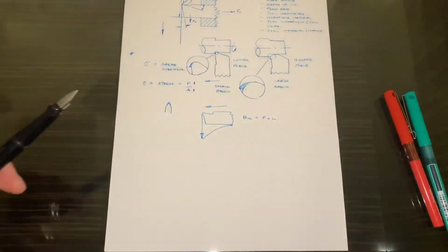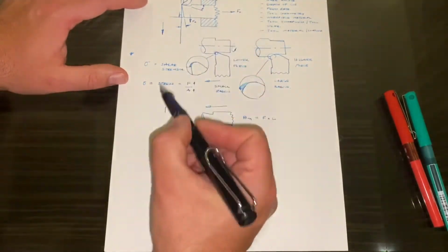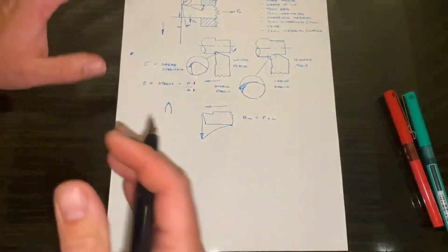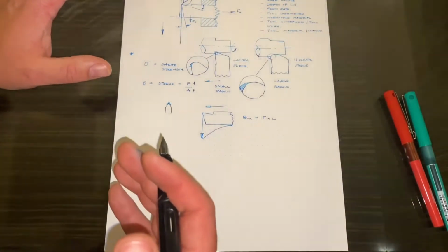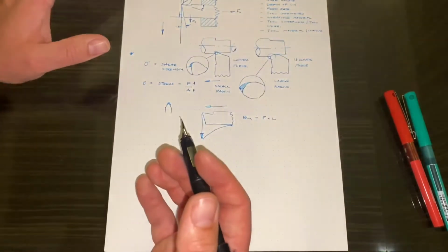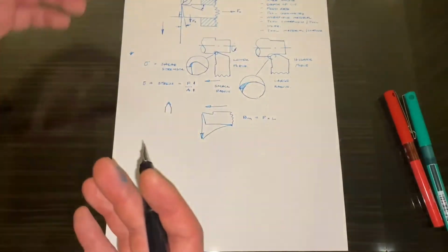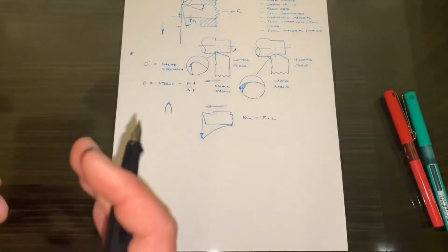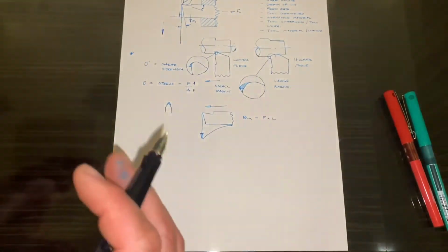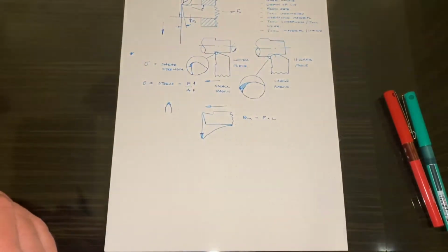And this isn't true, because what actually happens is that the tool does deflect during machining, and that will change depending on whether we're roughing or finishing. It will depend on the tool geometry, it will depend on the sharpness of the tool, it will depend on if it's cast iron. Sometimes you can have a hard skin on the cast iron, and then you get into the softer material, and all of this changes the dynamics of the turning process.